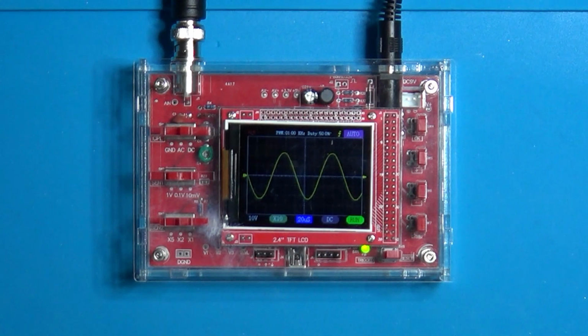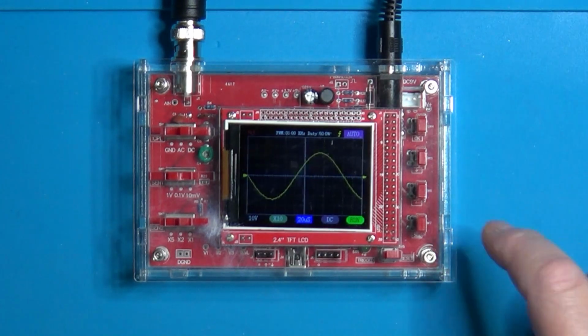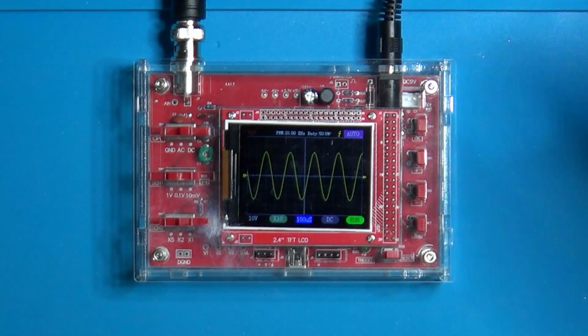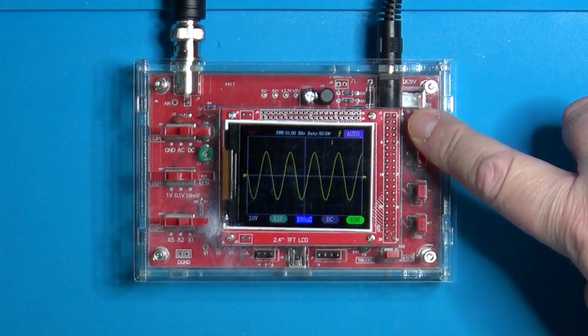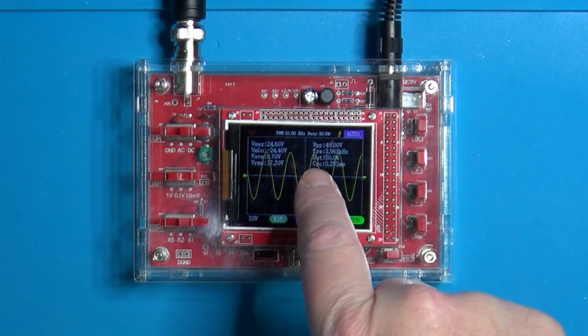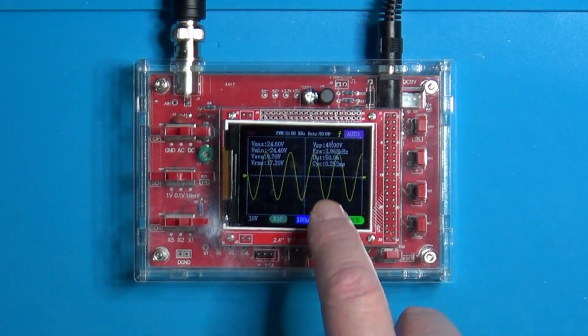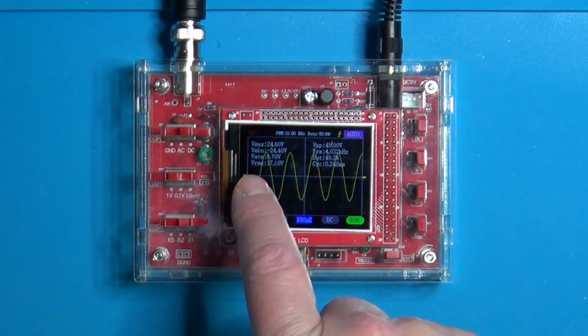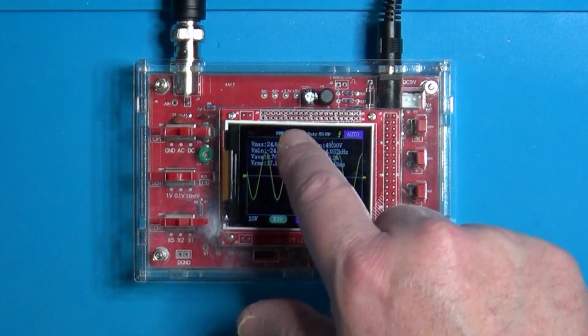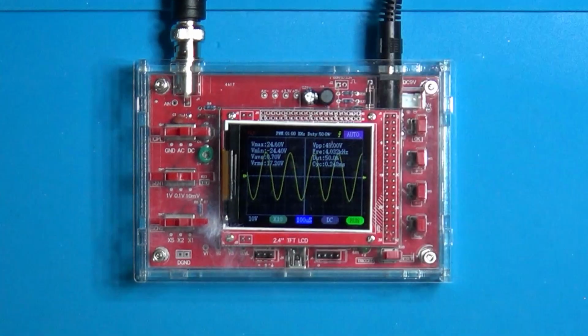It looks very good, but let's make some changes to see if the oscilloscope keeps behaving correctly. I'm now decreasing the frequency. It seems to work fine. Changing also the scale. Good so far. And now, if we push the top button for a few seconds, we should see the text information appear on the display. Here, like that, the frequency is right, 4 kHz. The voltage does not seem right, and that's because the oscilloscope thinks there is a ×10 probe. So let me change these settings.